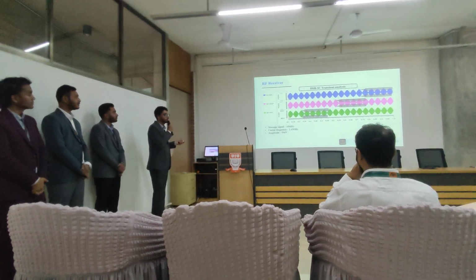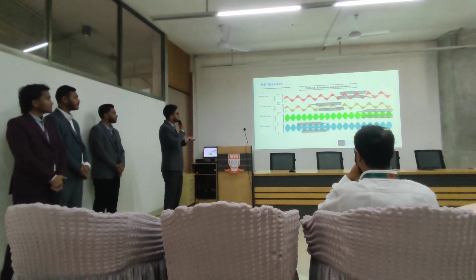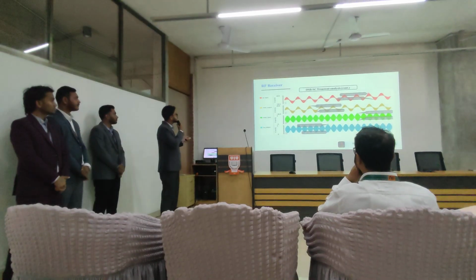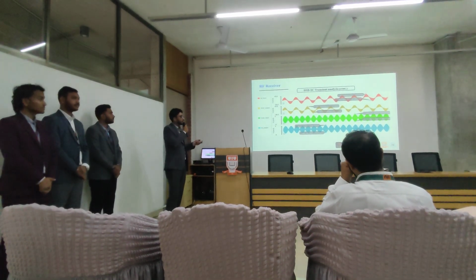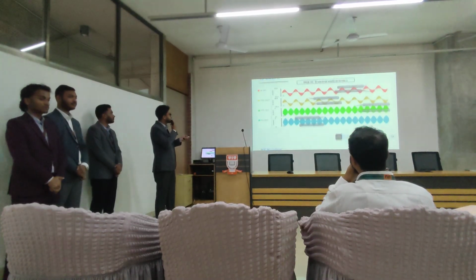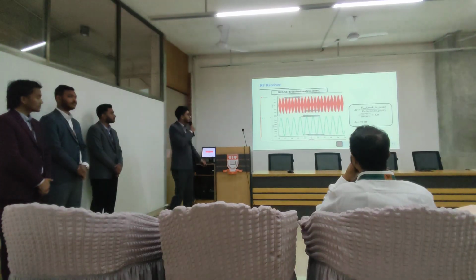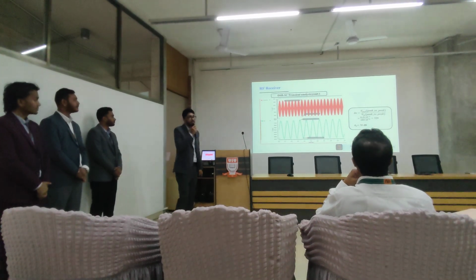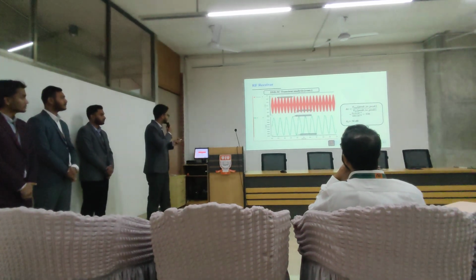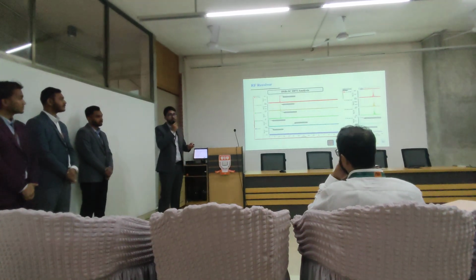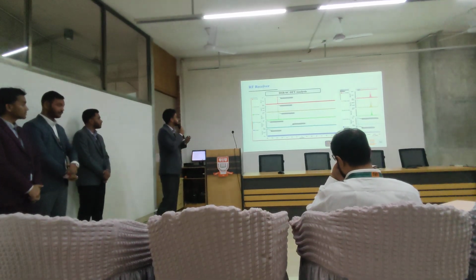First, the bandpass filter only picks the 2.45 GHz, and after that, the LNA boosts it and the mixer down converts that frequency into a baseband frequency, or a low frequency component. After this, the signal passes through a low pass filter, and we get our 10 MHz signal back. When we measure the output signal, we get a gain of 50 dB, which is 320 times higher than our input voltage. We also did the DFT analysis to confirm and ensure that our RF receiver block is working perfectly.